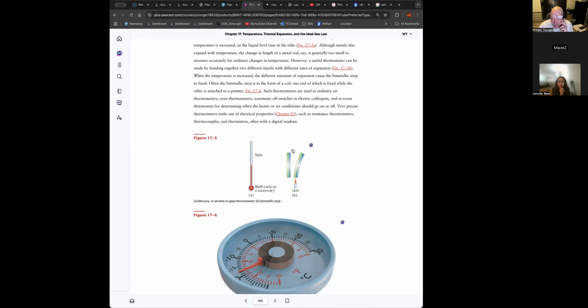And because each material, aluminum, steel, copper, all these different materials, or even compounds, they have certain characteristic properties, and those characteristic properties are a function of the material that you're using. So the fact that they're two different materials means it's highly unlikely, unless you're just unlucky, that the two materials expand at exactly the same rate. And by rate, I don't mean like a velocity.